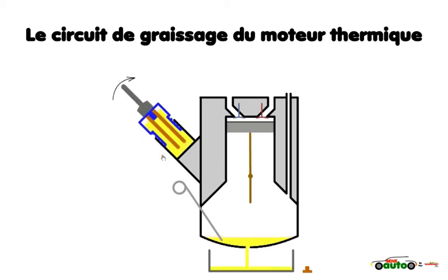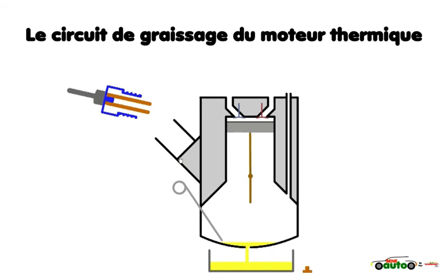This is a cartridge filter which is contained in a removable housing. It's sometimes called an eco-filter, as only the element is changed, saving on material and disposal costs. When the filter housing is unscrewed, a hole opens in the housing and allows the oil in the filter to drain internally to the sump.